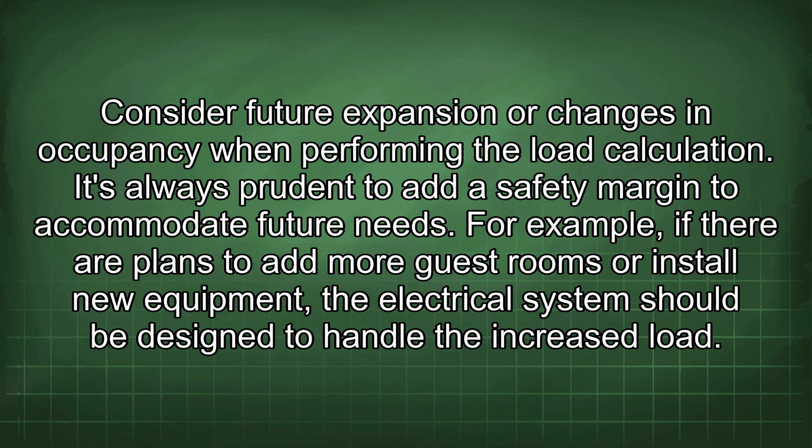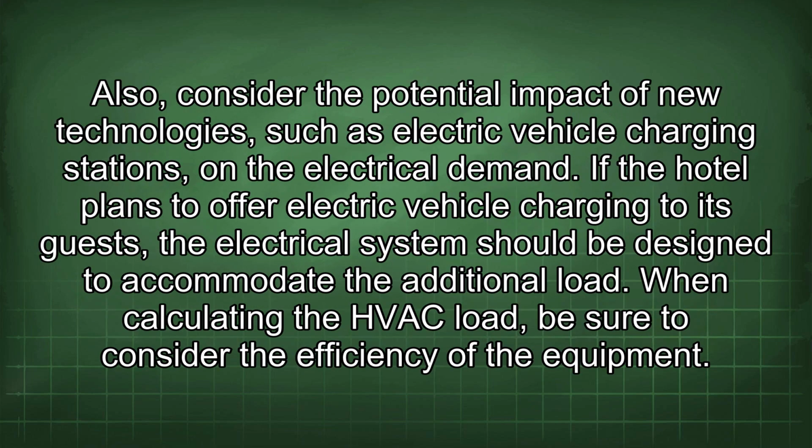Consider future expansion or changes in occupancy when performing the load calculation. It's always prudent to add a safety margin to accommodate future needs. For example, if there are plans to add more guest rooms or install new equipment, the electrical system should be designed to handle the increased load. Also, consider the potential impact of new technologies such as electric vehicle charging stations on the electrical demand. If the hotel plans to offer electric vehicle charging to its guests, the electrical system should be designed to accommodate the additional load.